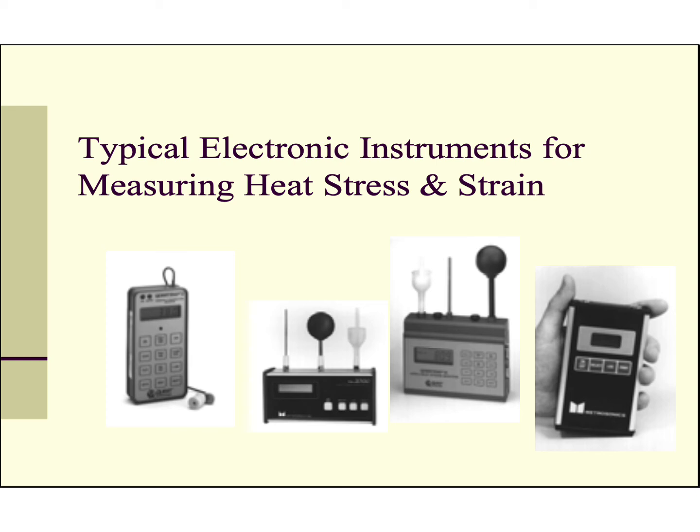The two instruments on the outside are for measuring heat strain, that is to say, measuring the effects on the human body. The one on the far left you can see most easily has an earplug with the thermometer inside it, so you insert that into the ear, and it's measuring the temperature inside the ear canal with it sealed to prevent influence from the outside air. So this is a pretty good approximation of body core temperature, and the instrument can be set to sound an alarm if the core temperature gets too high, or to provide a data logging function so you can monitor the human response to the hot environment.